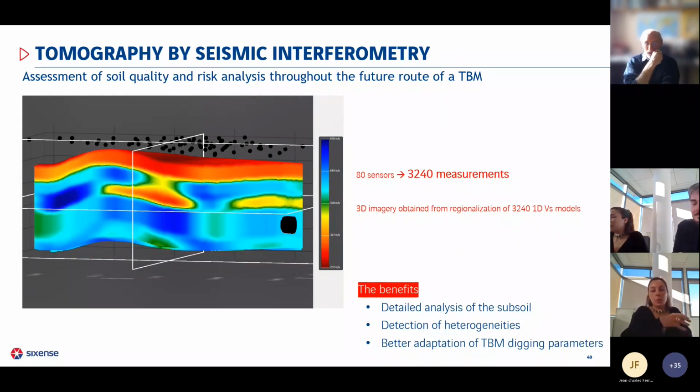We extract different examples in the whole area to analyze them, to check where we see the fundamental mode, if there are higher modes, etc. But then we program this picking automatically, after analyzing different examples and defining the ranges of frequency, the ranges of velocity, etc.